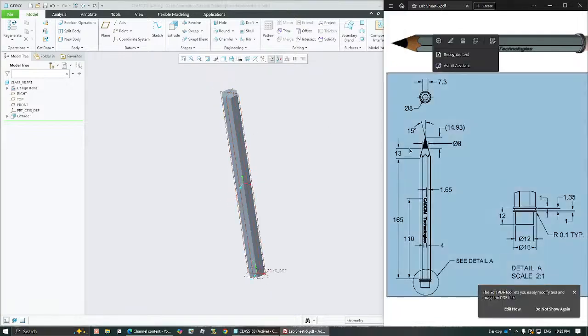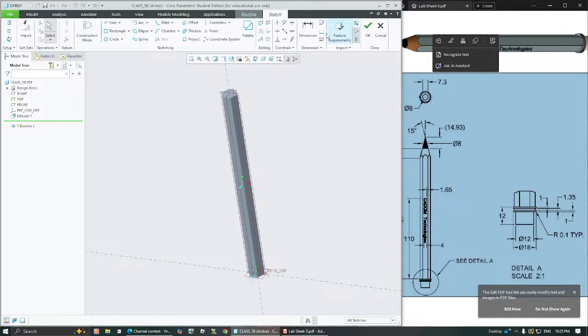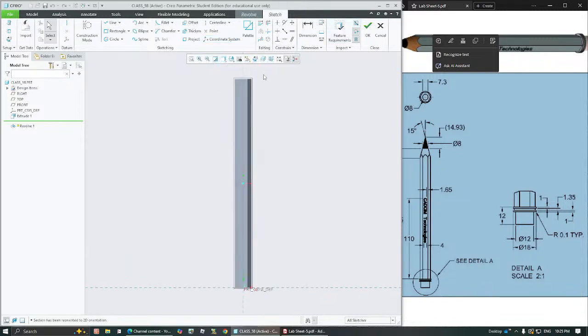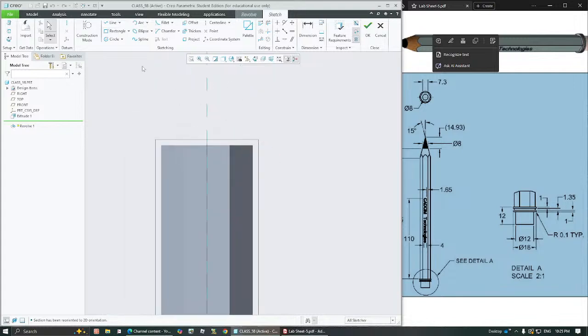Now from the top we need to subtract for a distance of 13. So choose this plane, go for revolve. We are going to do revolve cut. So make it normal to the view, and you can just expand. Click Control and mid mouse button to expand this.